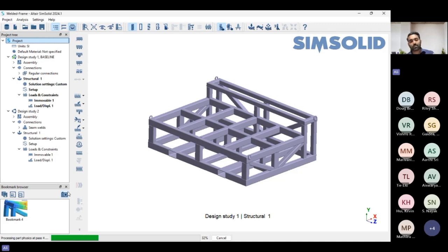By default, it takes about 3 to 4 passes to give good results, right? So more passes doesn't mean that it will give you much better results. It might have basically much more noise around the connections. So basically 3, 4, or 5 is a good number to start with. Even the software suggests which one is the best one for your kind of solve,